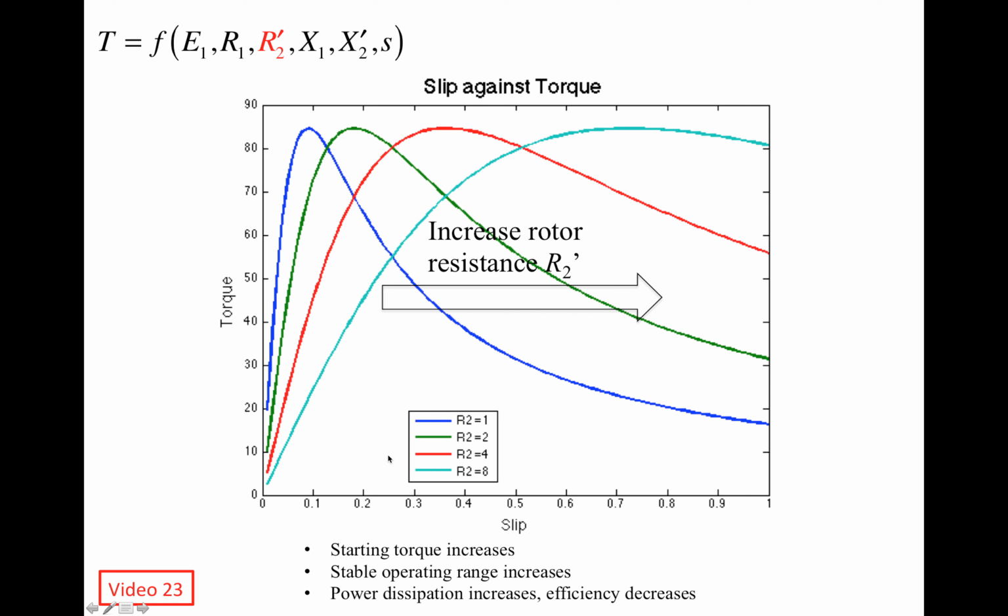If the stable region extends, the machine is going to allow the slip and also the rotor speed to vary within a wider zone. So by connecting an external resistor, it solved both problems. It has extended the stable region, and it provided means for controlling the current so that the generator won't burn.